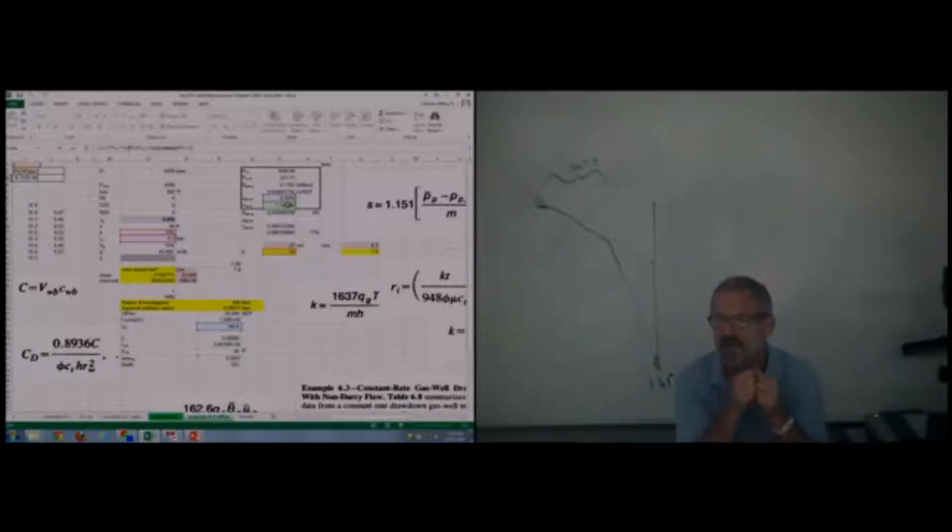So the type curve that we're using here, is it the same concept as the modeling that we use in the software, or is it different? We're looking at analytic solution based on dimensionless variables. And we can put our real-time data over those things just using some arbitrary X and Y match. And then from the Y match, we can get perm. From the X match, we can get some combination of skin and wellbore storage.